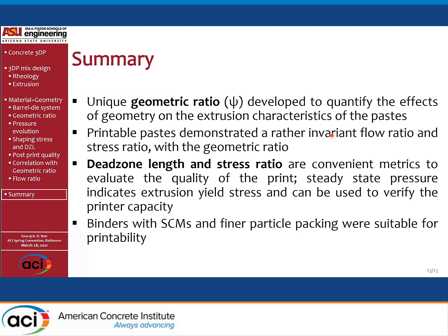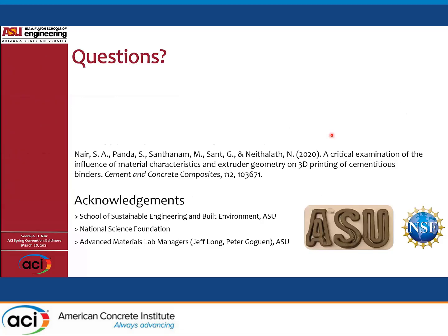So generally, again, binders with SCMs like the limestone and silica fume give better particle packing, and they tend to show suitability for printability. So more details are in this paper which we have published earlier, and I thank NSI for funding the research and our team for helping in this research.